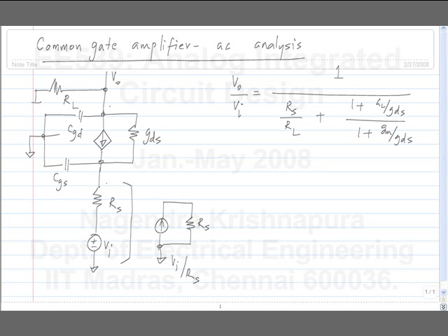Drain bulk and source bulk. These are junction capacitances from the source and drain junction to bulk, which also is incrementally grounded. Now, CGS and CSB are in parallel with each other, and CGD and CDB are in parallel with each other. Okay. So basically, there are capacitances between the source node and ground, and between the drain node and ground.